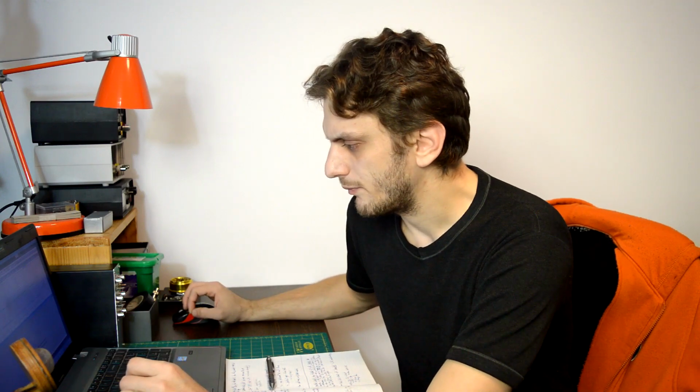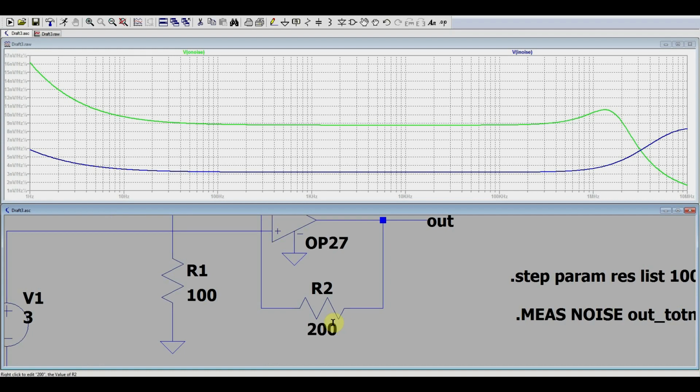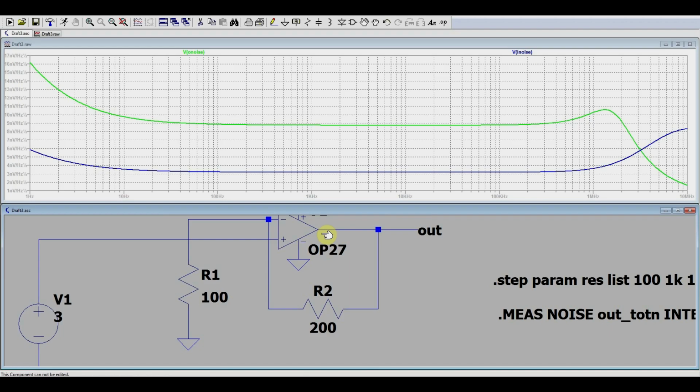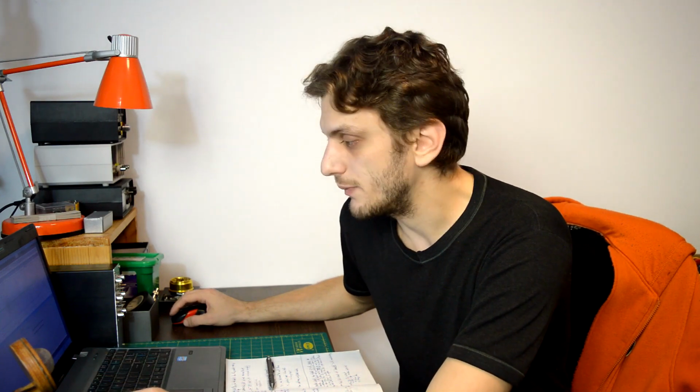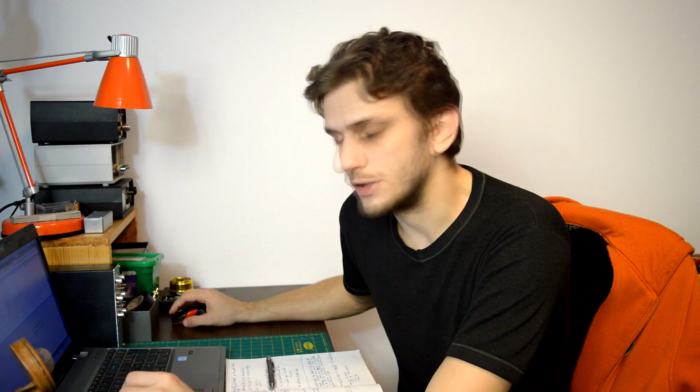Now, speaking of the noise coming from the various components, how do we know if the op-amp is modeled correctly? Well, we know that the resistor on its own will have noise, and LTspice models this. The question comes with semiconductor components or models that are attributed to certain components. Now, a nice trick that we can do is tell the simulation to not take into account the noise of certain components. This works well with resistors.